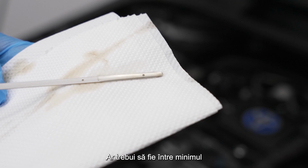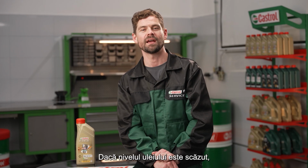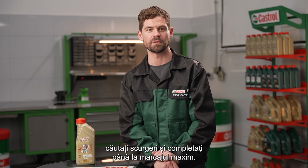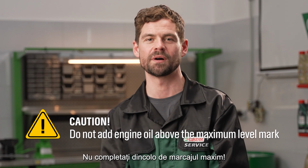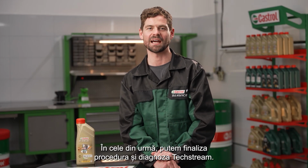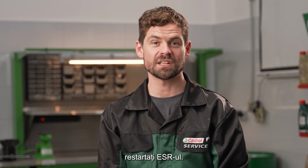Check the oil level, which should be between the minimum and maximum level marks on the bar indicator. If the engine oil level is low, check for leaks and top up to the maximum level mark. Be careful though, do not top up above the maximum level mark. Finally, we can complete the TechStream procedure and diagnostics. To confirm that you performed the maintenance, restart the ESR.